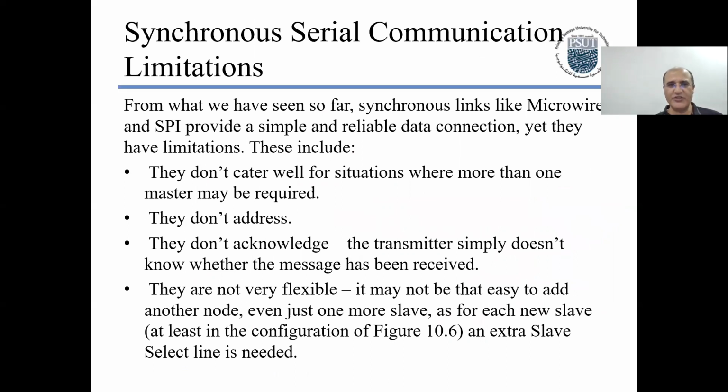Some of these limitations, like in SPI or Microwire: you cannot have more than one master. It's only one master and multiple slaves. The master is the one that can send and decide. You cannot have two masters. And there is no addressing, only the select. You select one and you send to them. It's not like you send an address.